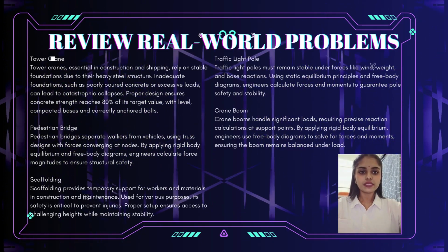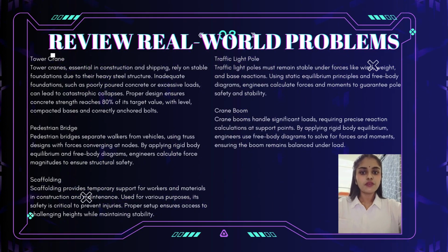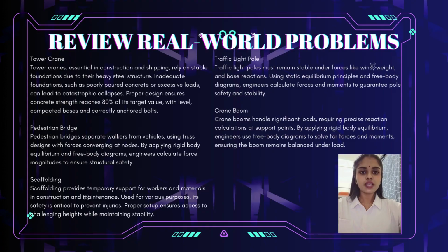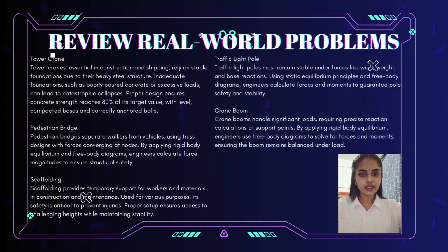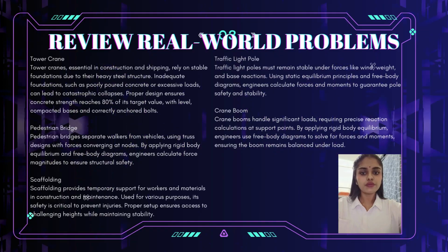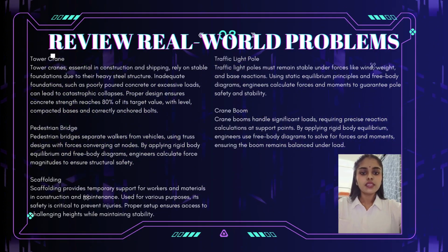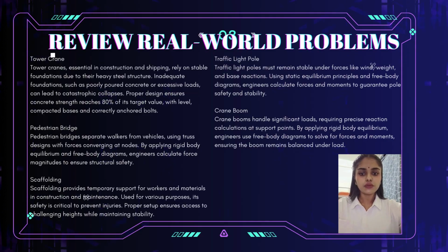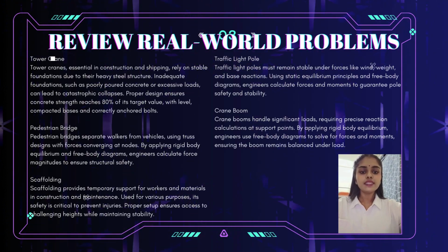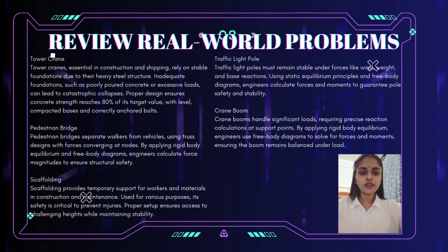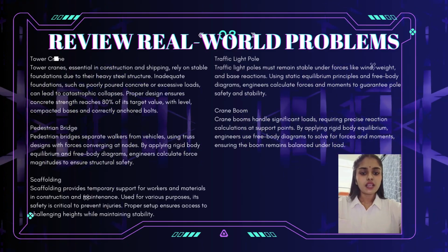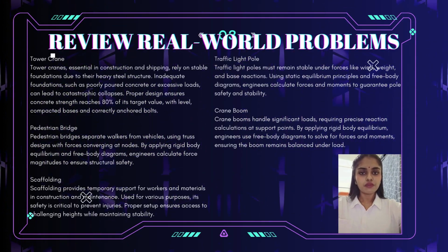Scaffolding must support workers and material without risk of collapse. For example, in construction, scaffolding provides access to elevated areas. Statics is used to calculate the forces acting on the scaffolding, ensuring it is reinforced to prevent structural failure and protect workers. Engineers analyze the forces acting on the individual scaffolding components. They calculate the distribution of these forces using the equilibrium equations, summation of Fx equals 0 and summation of Fy equals 0, and design the scaffolding to withstand the load without failure.